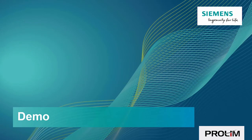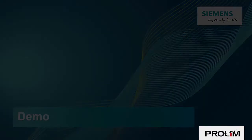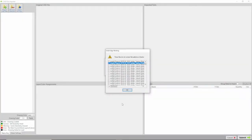Let's go back to our demo and see how 2D nesting is doing. 2D nesting has discovered several files that do not have flat patterns or blanks. That's understandable because many of these files aren't sheet metal products. However, the list will be saved in the log file so that if we are missing a shape later on, we can go back and look at the list to determine which files we are missing.